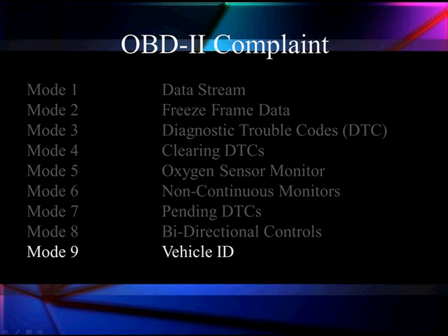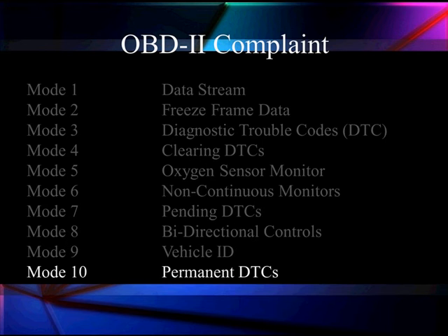Some of you may be working on vehicles where the TSB has not been implemented yet, and they may be of value to you. They give you some good indications, stuff to look for. And mode 10 is an inspection and maintenance mode. It's modes that only clear after the vehicle has recorded 3 good trips. If you disconnect the battery or try to clear codes with a scan tool, they will not clear.